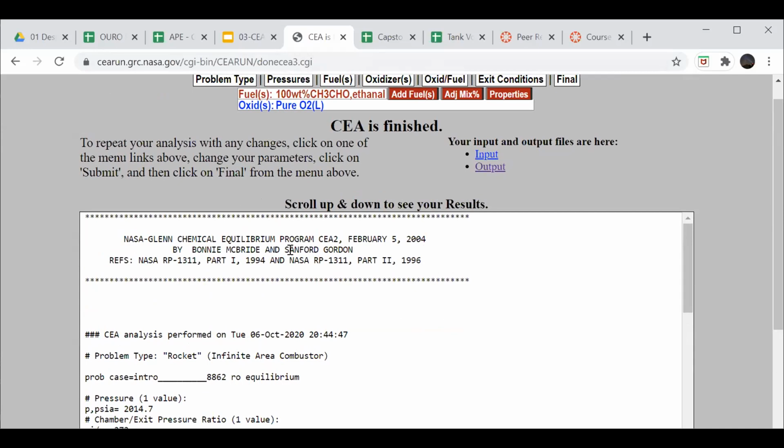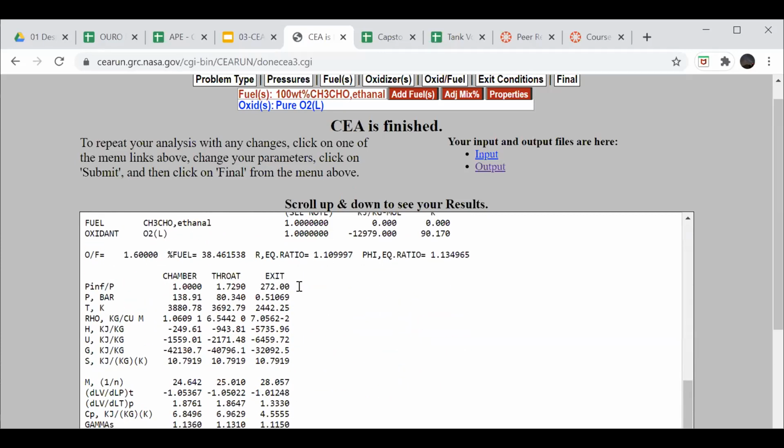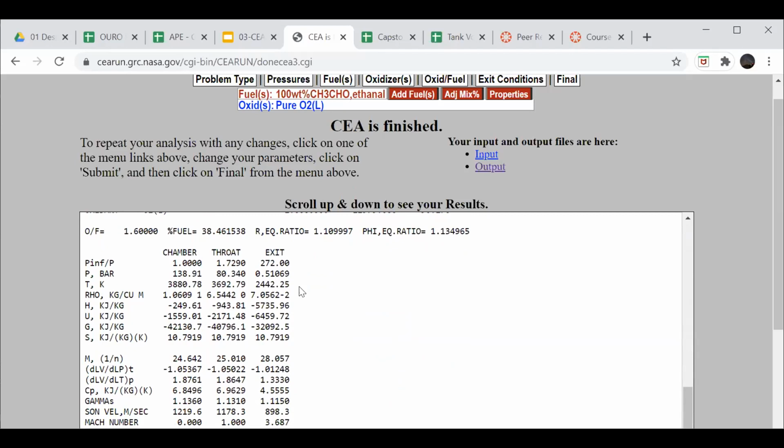What's a realistic minimum pressure to have for our exit pressure? You cannot get supersonic flow at sea level with less than 23 psi. So that is your absolute minimum. For your chamber pressure, yeah. I meant for the exit pressure. Oh, exit pressure. I don't actually know. If you get too low, you could break the nozzle and explode. I don't have any math on what that is, and it depends on how beefy your nozzle is. If you're trying to run this at sea level, you don't want to design it for more than like 5 to 6 psi away,